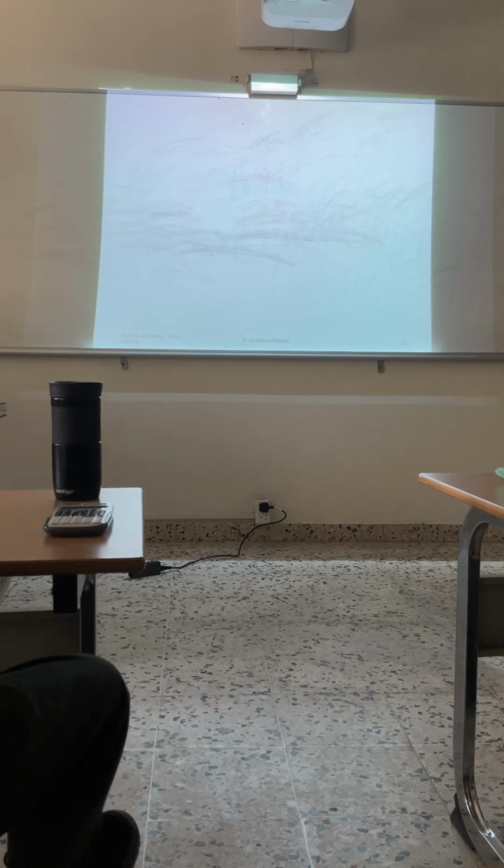What is the third technique? Pull. Pull. All? No, before the all. 2 or 3 masses, such that the resultant of the balancing masses will be acting in the counter direction of the unbalanced force. You end up saying summation of force is equal to 0. Okay? All these kinds of techniques are applied in one single plane, which is the plane of the unbalanced disk. And this disk could be a gear, could be a pulley, could be a sprocket, could be anything.